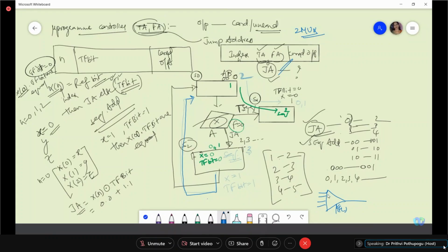Here, what we do is, after choosing the qualifier, we will be taking the qualifier values here. Now, the first mux input, we try to take it as default true. True means 1. Why? Because the other test variables will be taken through this. Except the first one, the remaining inputs of the muxes will be given one of the test variables.